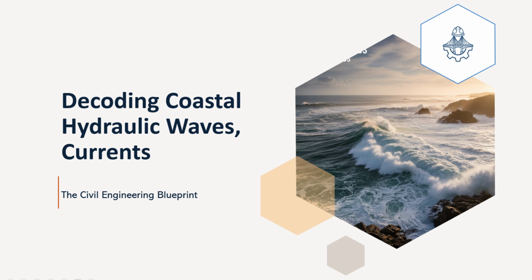That's right. And just a quick revisit, as you said, to reiterate that wave diffraction is that lateral spreading or transformation of wave energy. It's what allows waves to bend around barriers and spread into what might otherwise seem like calm shadow zones behind breakwaters or islands. It creates complex wave patterns in harbors and lee sides of structures that engineers must predict for effective and safe design. You might build a breakwater to block waves, but diffracted waves will still sneak around the edges, and you need to calculate their height and impact inside the supposedly protected area.